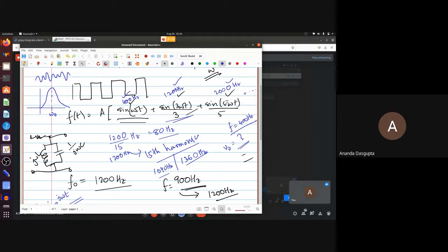You don't give in a particular square wave, you give square waves of different frequencies and then check where you get resonances. So instead of putting in 1200 and detecting outputs at 1200, 3600, 6000, and so on, what you do is put in 200, 1200, you get a peak. Then you put in 400, or actually you keep on changing the frequency until you get a peak. The peak will happen at 400. And then you will get 1/3 of the amplitude. So this is done in quite a different way from what the Fourier series expects us to believe.